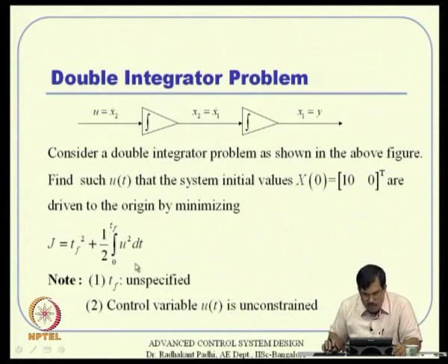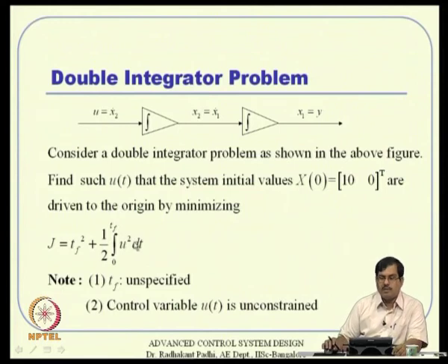By the way, this control magnitude minimum is also a significant property of satellite control, because the control availability is limited there. Either you talk about RCS control or you talk about reaction wheel, things like that, the control amount is not infinite. I mean, you are severely constrained by control availability. So, we want to minimize the control effort, and we want to do the job as quickly as possible actually. Okay. So, that is why I have selected the cost function that way.